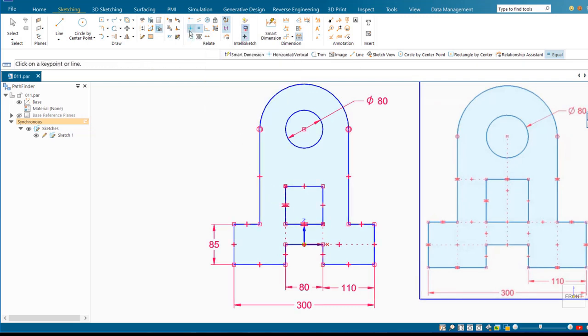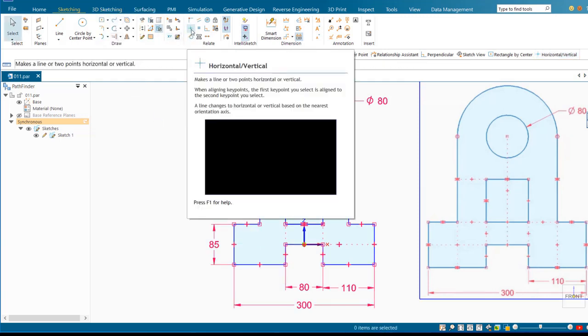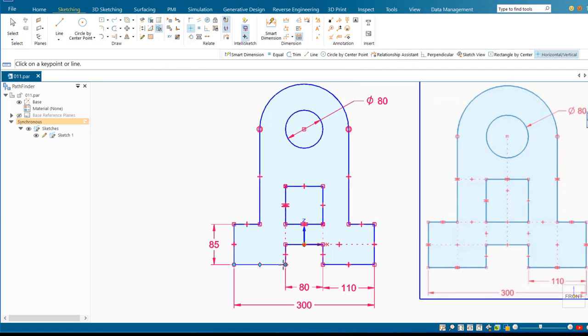And then I know that this line is the same height as that. This line is the same height as that. And that sort of flipped things out down there. So I could just hit undo and straighten that out first. So maybe that's what I should do. Come and just set this up and make that align with that. That align with that. And so I'm just doing horizontal verticals all over here, so things won't move unpredictably like they just did.